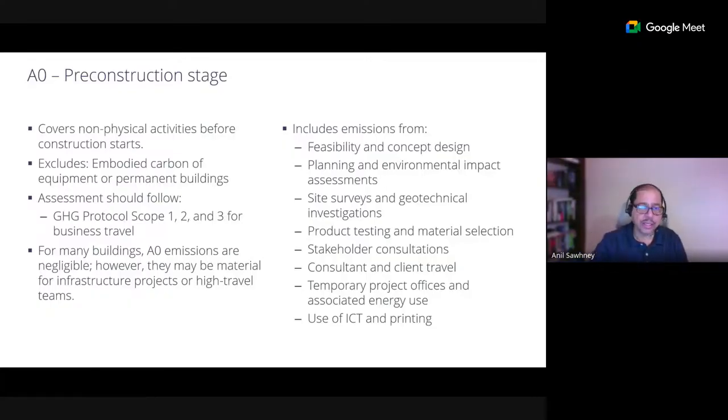Our standard says that under this calculation, A0, you need to cover all non-physical activities before construction starts. So you're on site, construction has not started. Any emissions that take place, maybe for surveying, maybe under soil investigation, maybe under any other site visits and so on, should be captured under A0.